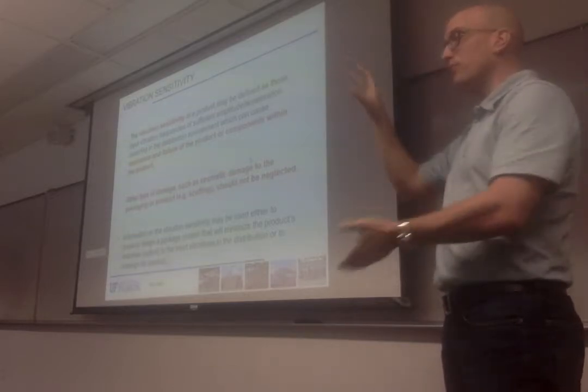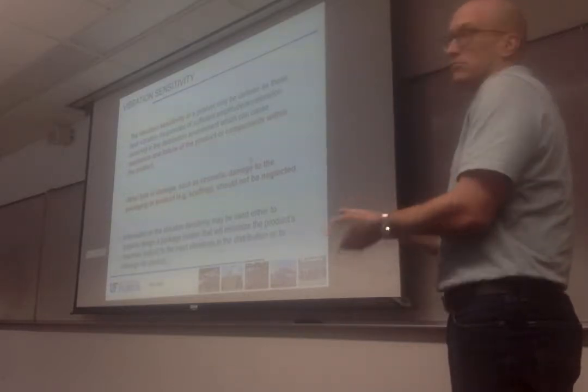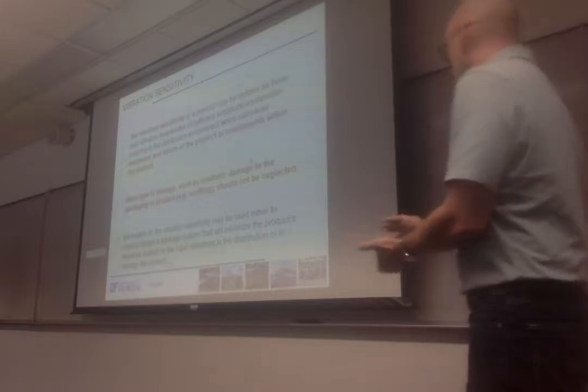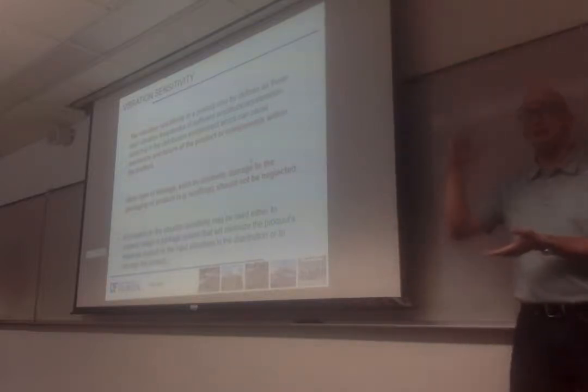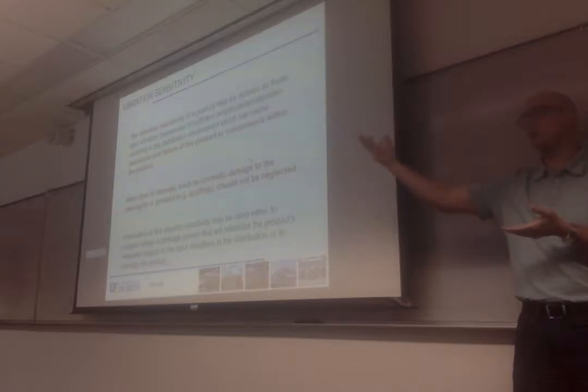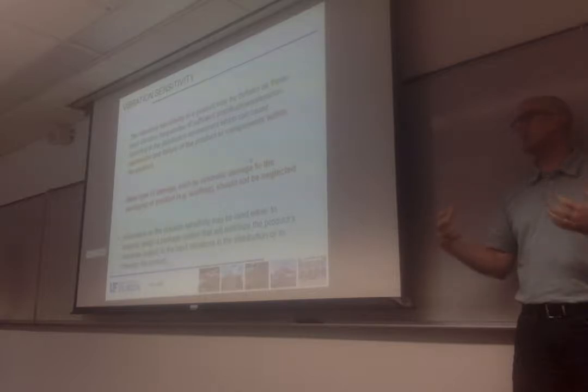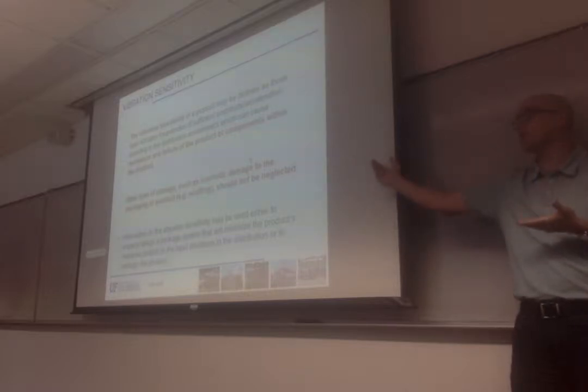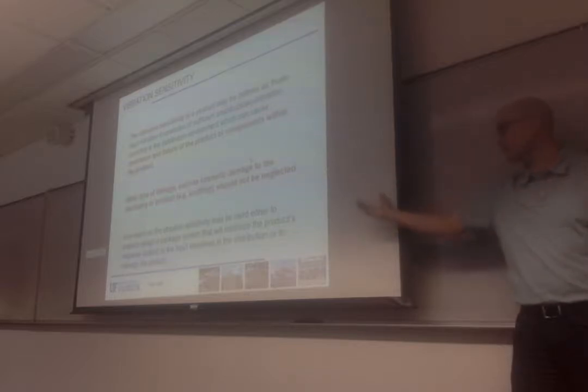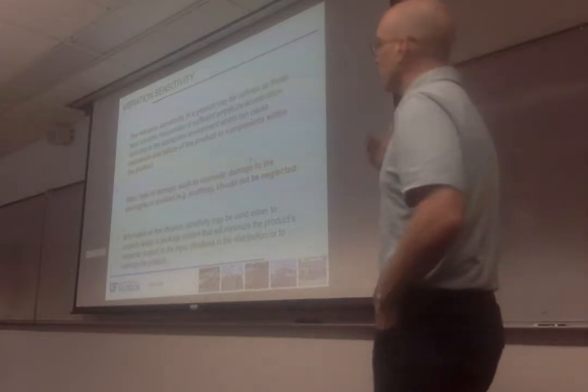The box on top will vibrate differently than the box placed under it, okay? And you may have different failures. You may have some that are due to compression, some may be due to excessive movement, okay? But if it's something due to vibration and road transportation, you should have a lot of it. Unless sometimes it happens over a very long period of time, then you're going to have, again, systematic failures for long shipments, okay? But it has to be the same thing or very similar, and it has to be encountered continuously.